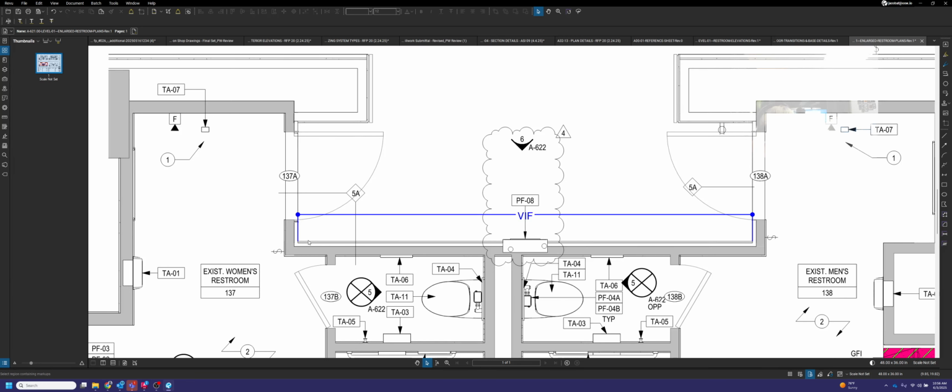And what that means for you is that the project manager and the building superintendent that we have hired on for the job will go into the building prior to anything being constructed, and they will pull tape measure measurements off the walls and check to make sure what this actual wall-to-wall dimension will be. It's really important that we do that because when we get out to the field and we check all those dimensions, that means that we can actually construct our panels to the exact opening size between these two walls.